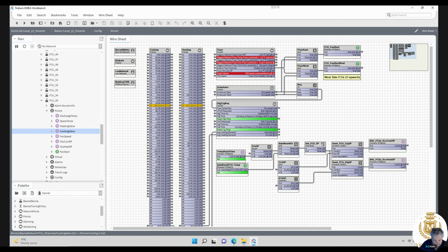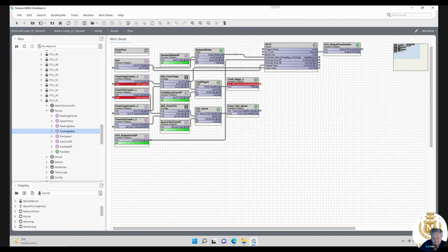So apparently 55 wants heating. So does 42, 37, 36, and 16. Not too sure why that would be when the majority all want cooling. Now I don't know what temperatures on this floor do I? I ain't got a floor temperature there or the parts per million there.